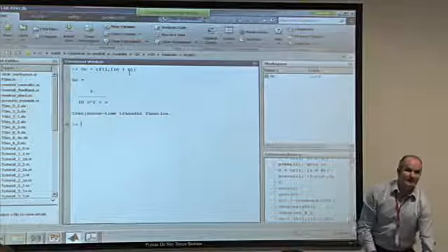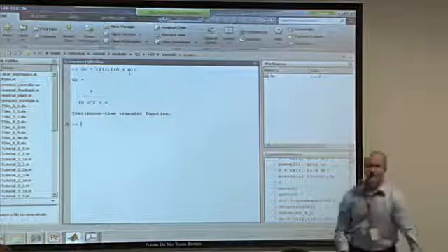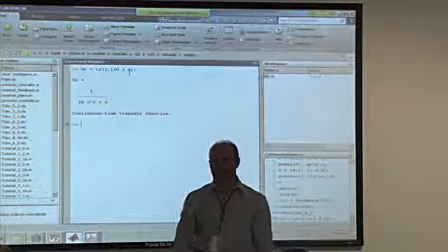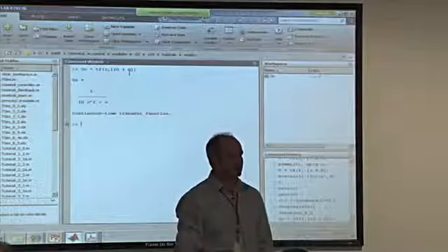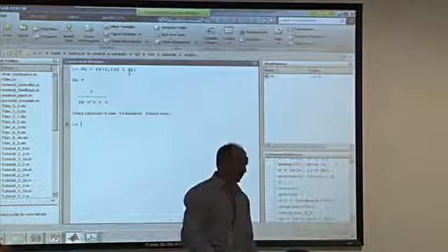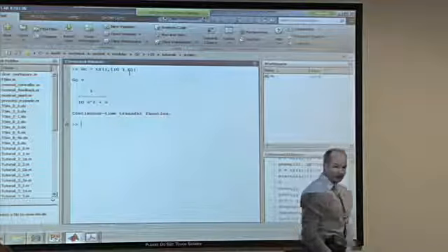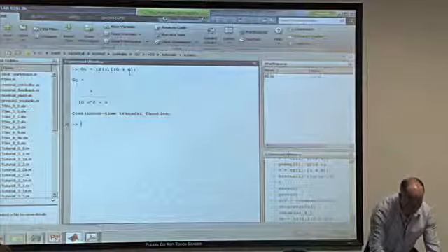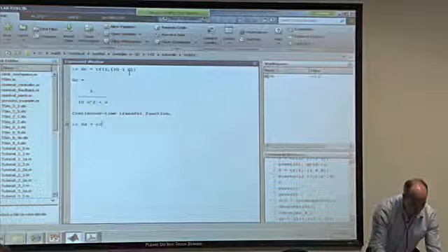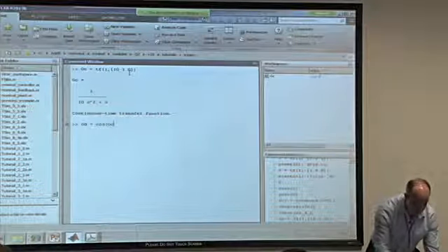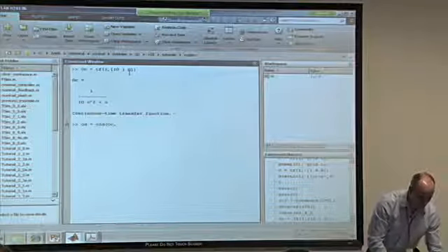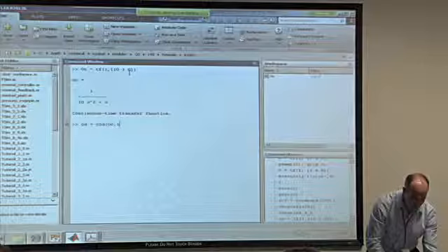And now what we'd like to do, well, what are we going to do now? What's the next step? Discrete transformation, what method shall we use? Zero order hold, right, because we want the zero order hold phase effects to be taken into account. So we'll create a transfer function GD for discrete, and we'll use C to D. We give it the transfer function that we're interested in. Now, it did tell me the sample rate, and it's 1 hertz, so that's nice and easy, 1 hertz.